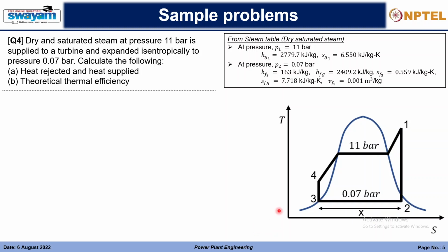So the heat is generally rejected in the condenser section. So this is the condenser, 2 to 3 is the condenser. Here the heat is rejected to the ambience, or whatever the condition is in the whole Rankine cycle. And the heat is supplied in the boiler, right? So from burning the coal or using other fuels. So that is how the heat is being supplied.